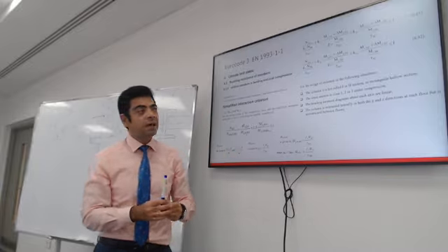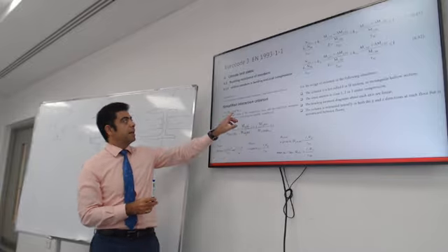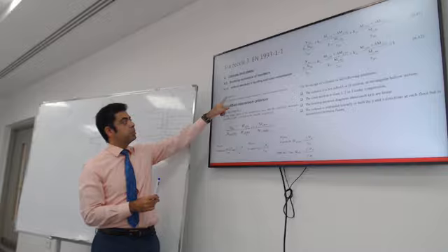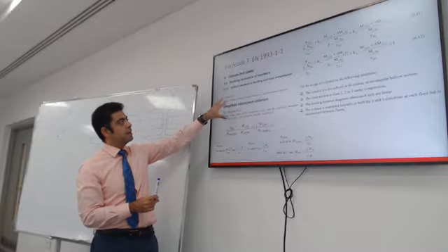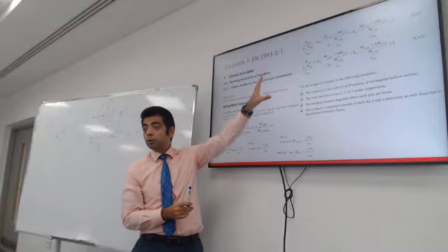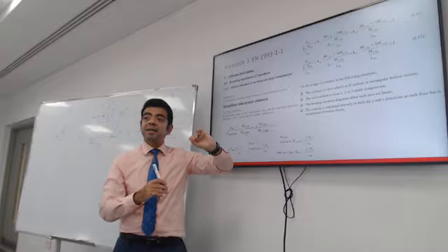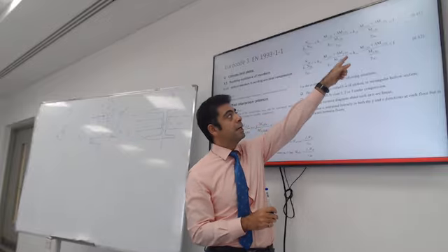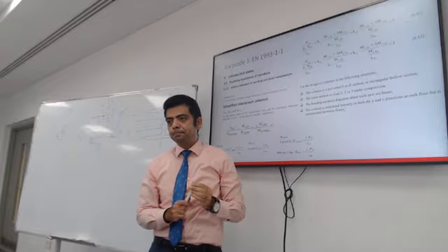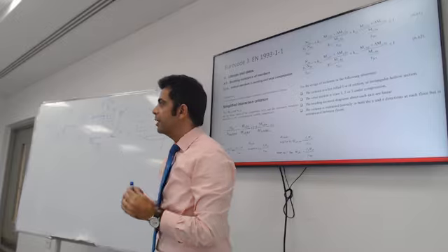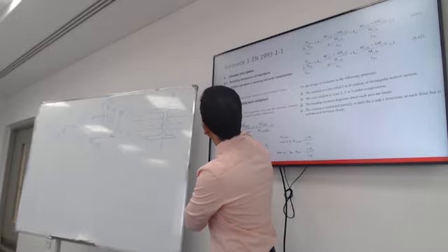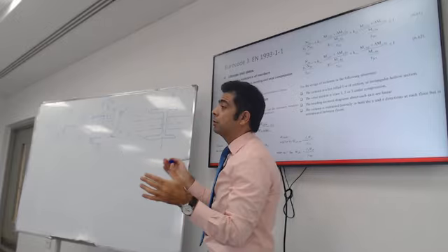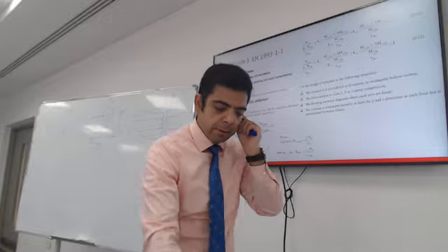I just want to point out that this equation is in a supplemental document. It's a document that comments on the Eurocode that simplifies a little bit the calculation of the K factors. So when you go look for it, look for this document. It's the verification of column in simple construction.